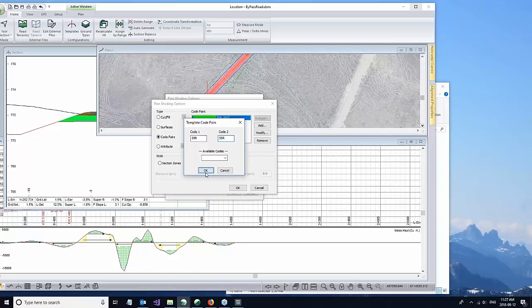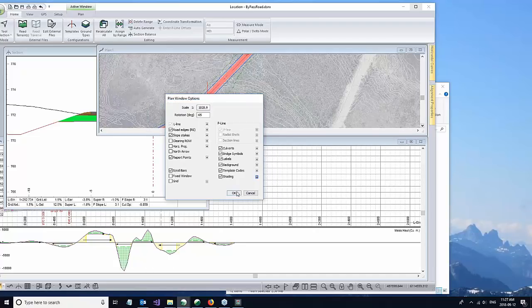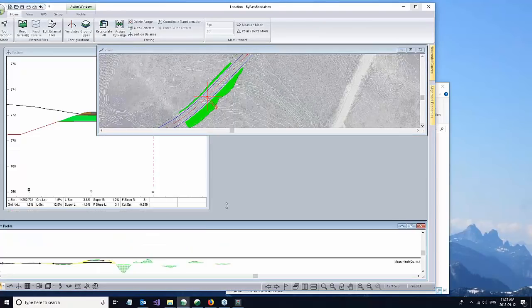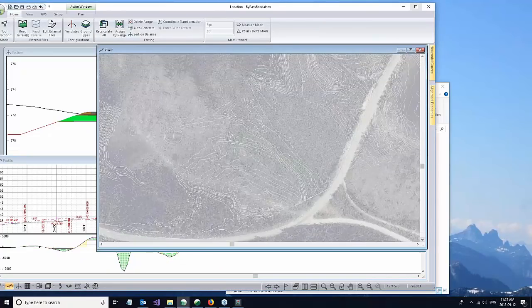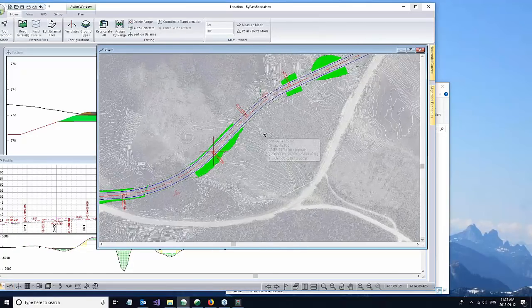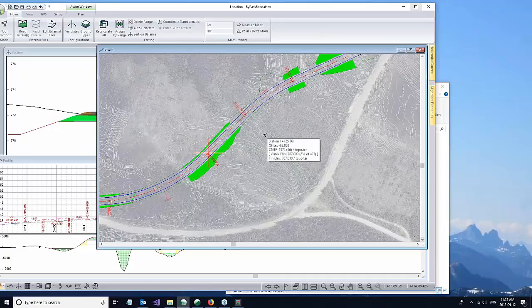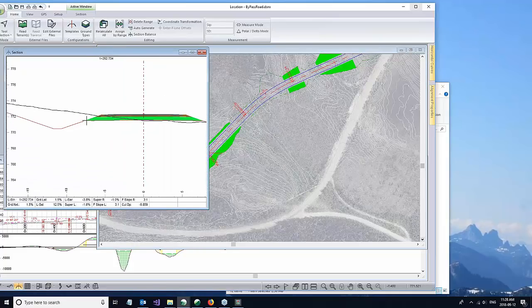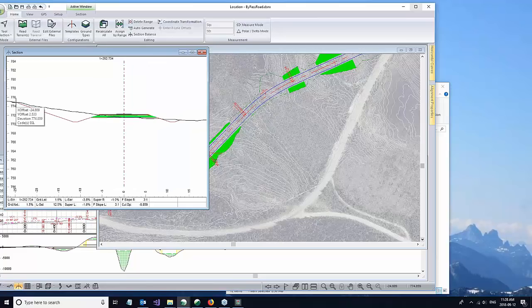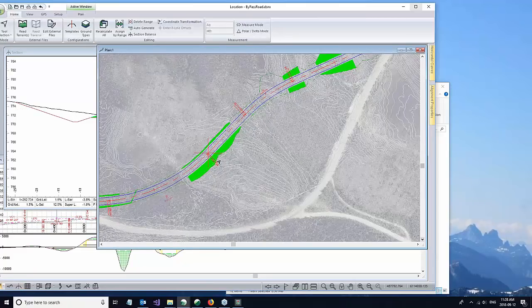SSR. So ditch inside left to SSL, ditch inside right to SSR. Just go ahead and draw that. And there you can see quite graphically where your ditches are by choosing point codes. And this can be applied to other things: areas where you're doing resurfacing, retaining walls again, anything you want that is captured in the template. So I've gone from ditch inside at that point there to that point there, SSL. So that area might be of interest to me because it's an area that I have to seed, whatever.